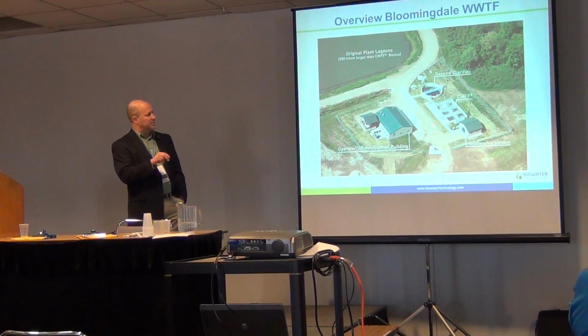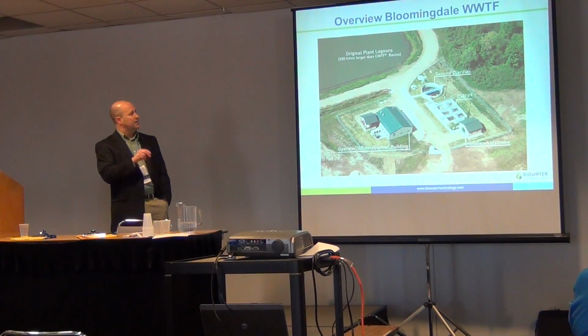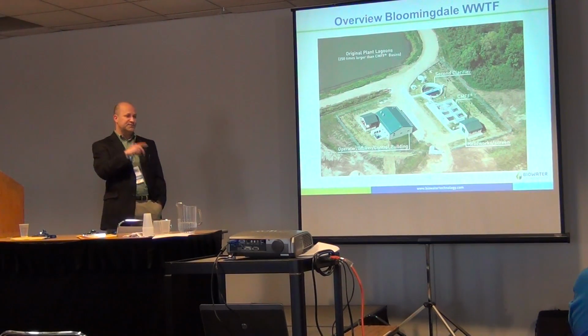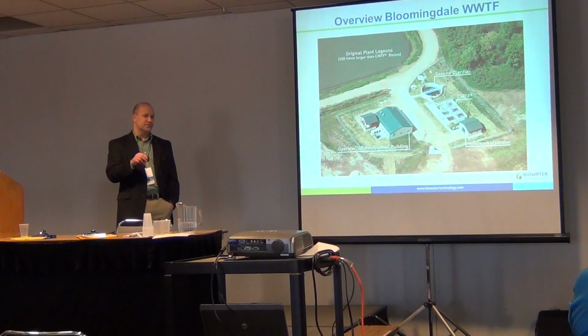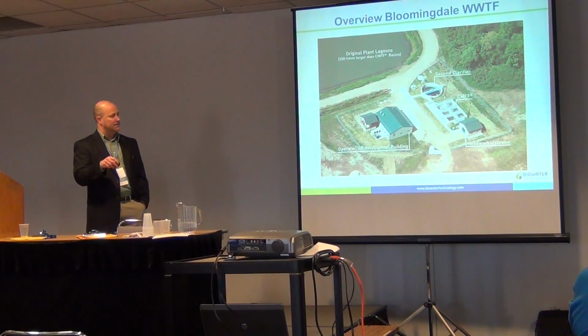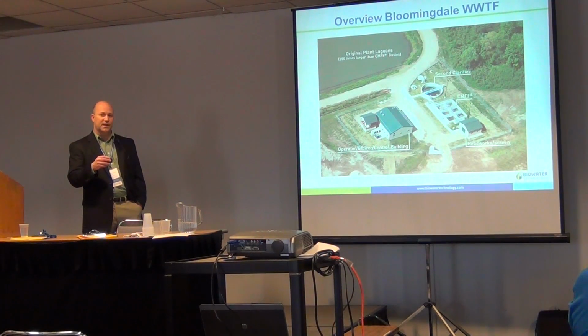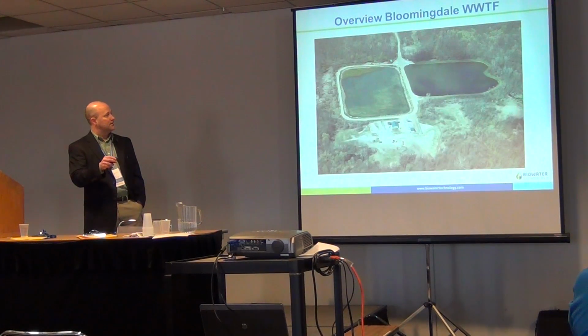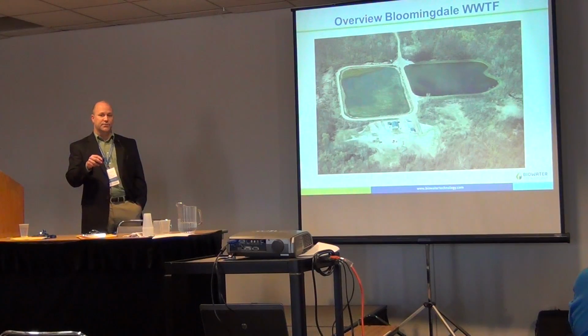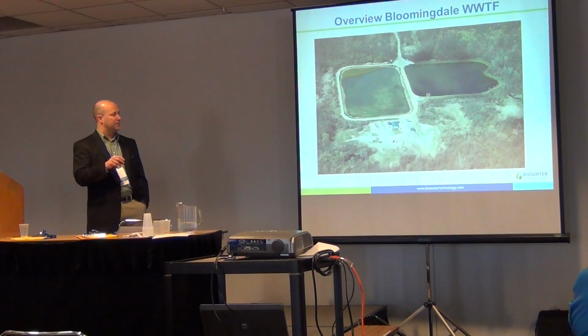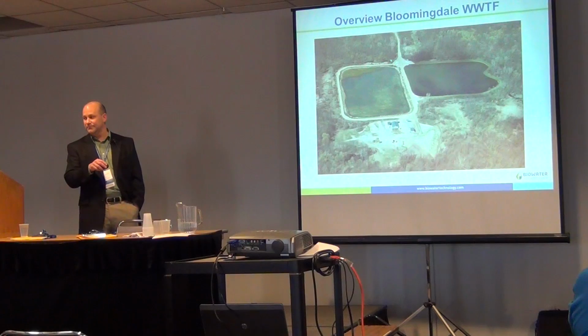Interesting to note that the biological treatment area right there is 250 times smaller than the lagoon system. So to emphasize the amount of footprint that an MBBR takes up, this is 1/250th the size of those lagoons, and it's doing BOD removal, nitrification, and with chemical enhancement, phosphorus removal.